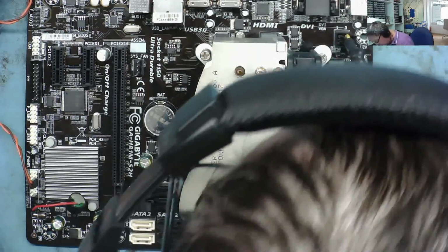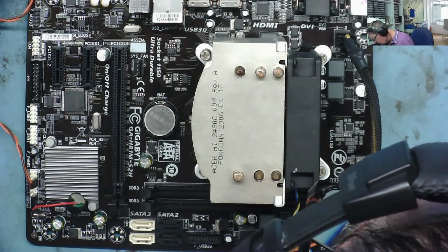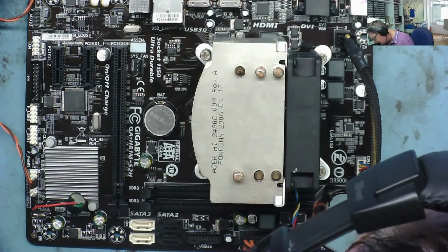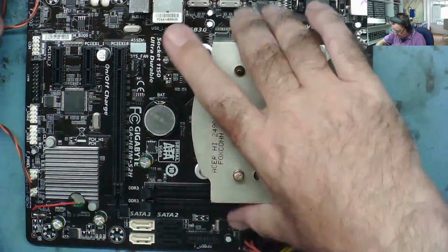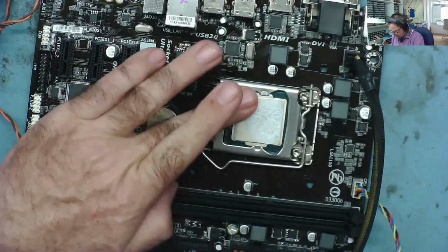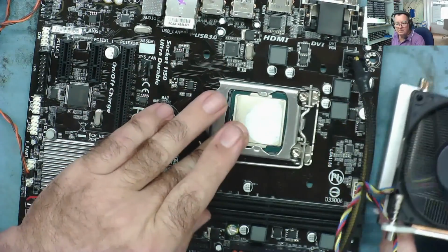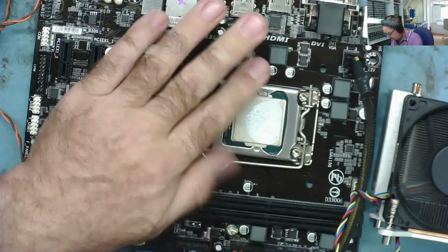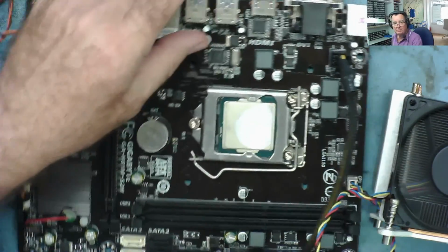Yeah, it's kind of stuck in this loop where the fan's powering on and off over and over again. Yeah, this is basically what it was doing before. The CPU's cold. You can see the fan there. CPU's cold, which makes me think there's probably no V-core. So that's the first thing we can check.